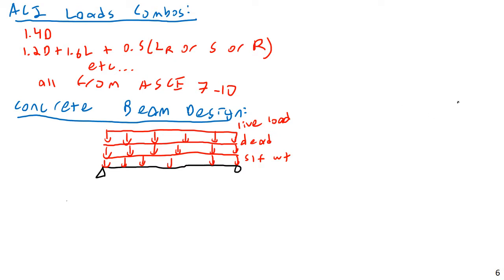I guess the one exception would be, I should rephrase that. If you had a tension member under a large amount of load, and that load was pure, and the tension member was purely vertical, and the tensile force completely overwhelmed the self-weight of the member, well, I guess that would be a pretty pure tensile member, in the sense that at no point along that member would you have any section in compression or in bending. But in anything other than a purely vertical member where tension absolutely dominates, you're always going to have some amount of bending. Anything at an angle, there's going to be some amount of bending.